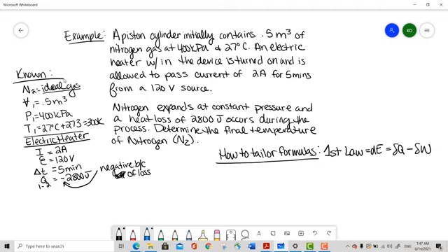And so we know again that we can break this down. What do we know about total energy? Well, we know that total energy is the change in kinetic energy plus the change in potential energy plus the change in internal energy, right? So we can put that all equal. And then let's look at it. Have we had any kind of mention of velocity? No mention of velocity. So we can omit this.